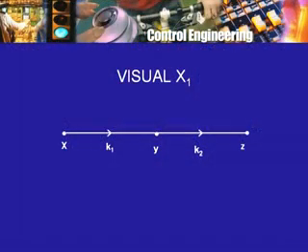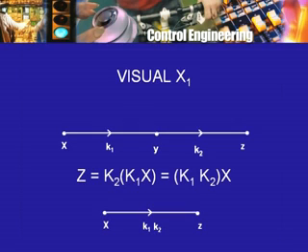Now what is the point of doing these transformations? Why are these transformations to be done or thought of at all? Because they simplify the graph. Here, for example, the graph had 3 nodes. After transformation it has only 2 nodes. But there is a flip side to it, that in doing this we have removed the signal Y. It may happen that the signal Y is also useful or required later on, and therefore what one does is one then goes back after you have worked with X and Z without Y, then you go back to Y, and that's easy because Y is simply K1X.